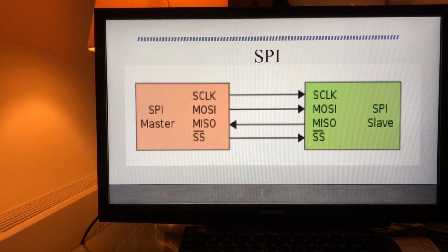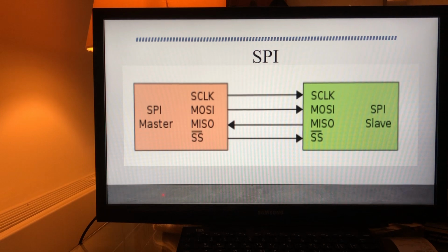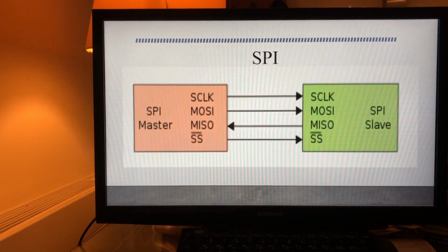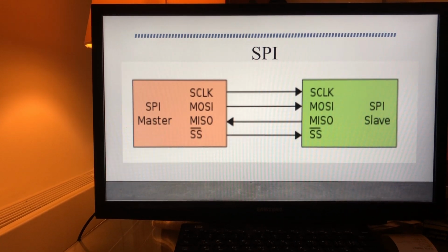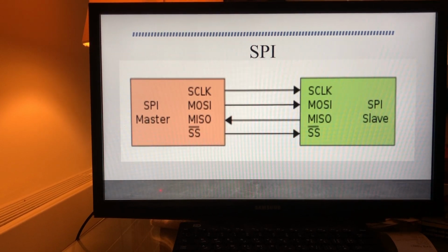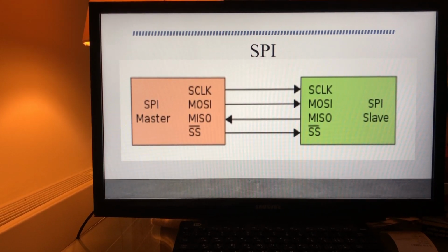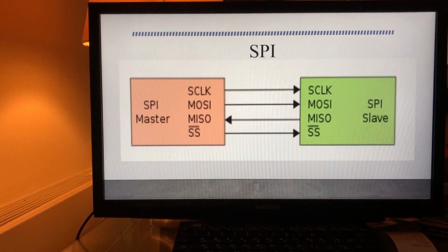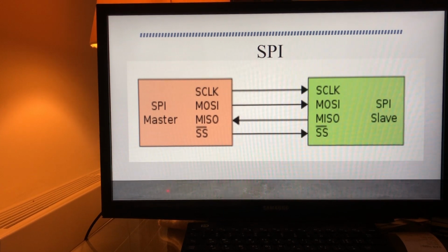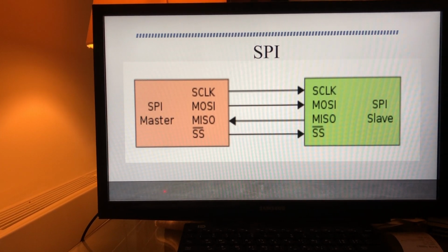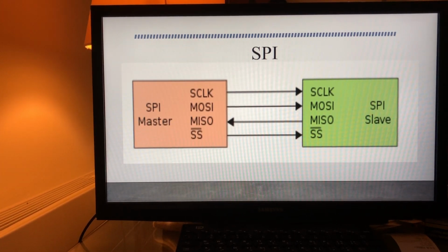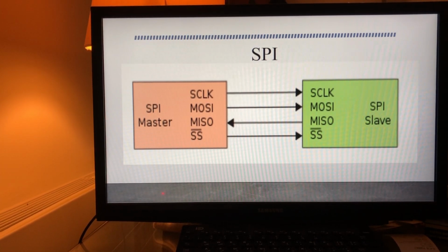The SPI is a full duplex protocol which sends and receives at the same time. In this protocol, it does not have to send an address, but there is a special chip select line that activates the device to be connected with. When the logic is 0 it activates the device, and when the logic is 1 it deactivates it. It's the most used protocol in controllers.